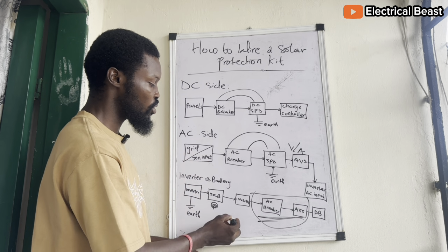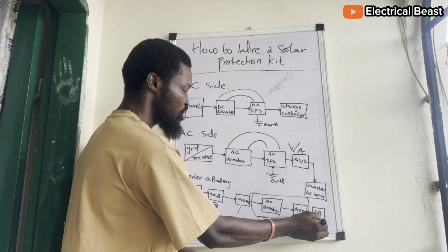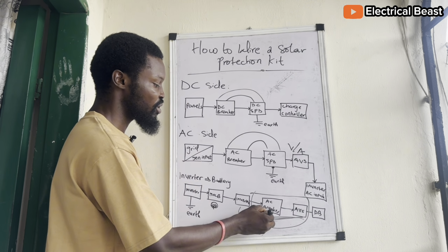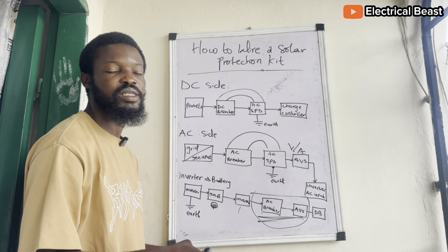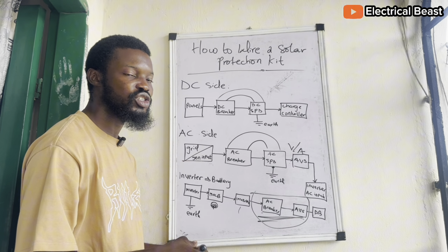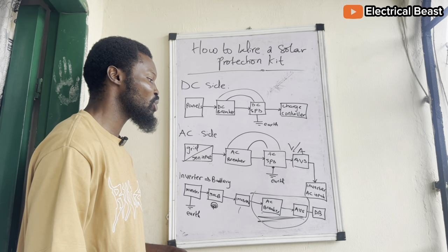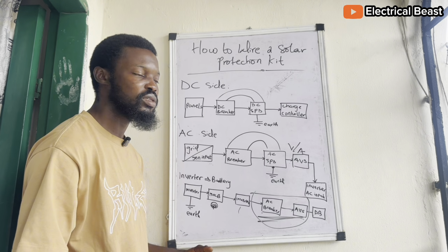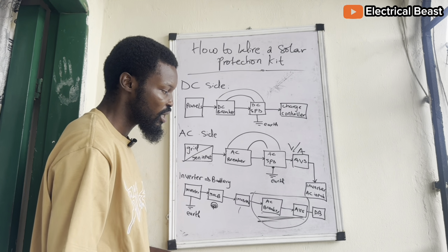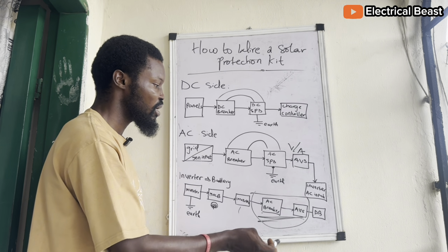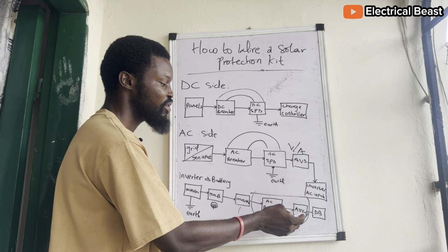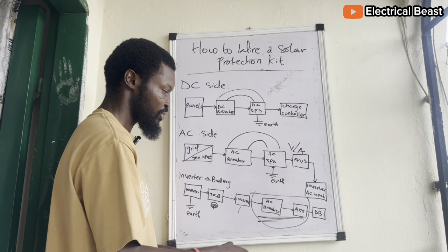They go ahead and connect the inverter straight to the DB. Some persons connect just the breaker to the DB. But in solar systems protection, there's no such term as overprotection. So if you need to add everything, if you have the means, just try to add the AC breaker, the output breaker from the inverter to the DB or even to the AVS, then also to the DB.